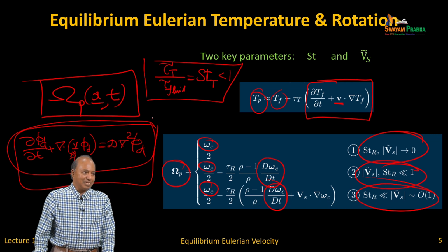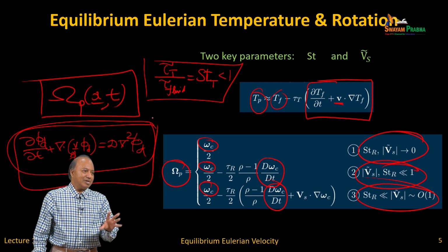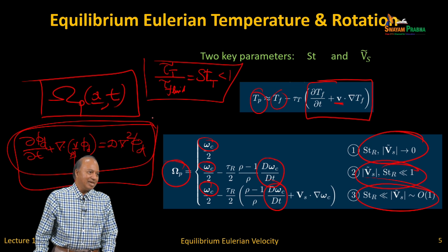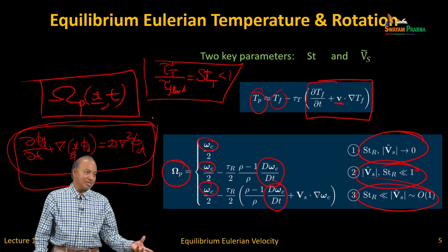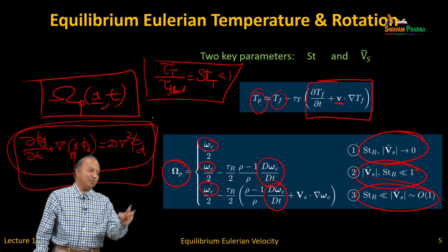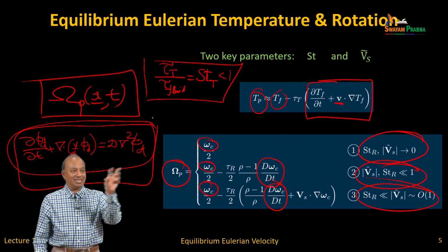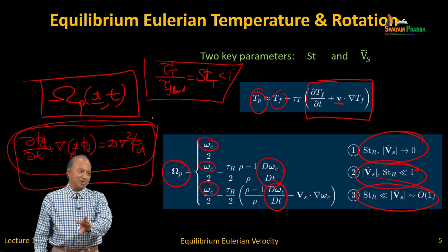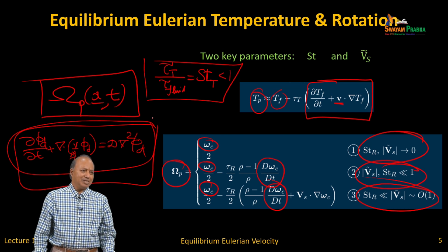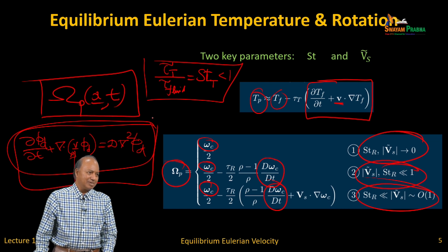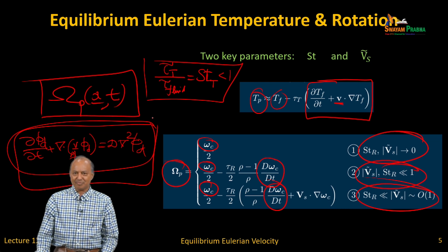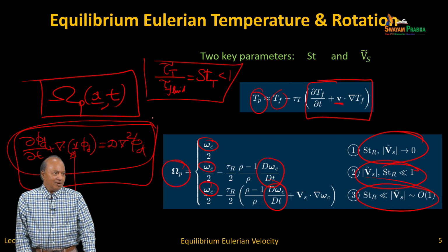Okay, that makes sense, because instantaneous quantities are fluctuating and hard to compare. And also you can compare not just the mean, but the RMS, to know whether the level of fluctuation you see in the experiments is the same as what you are computing. So not just the mean will be sufficient, but you may want to compare the RMS to see whether this is good. Yeah. All right. Thank you, guys.